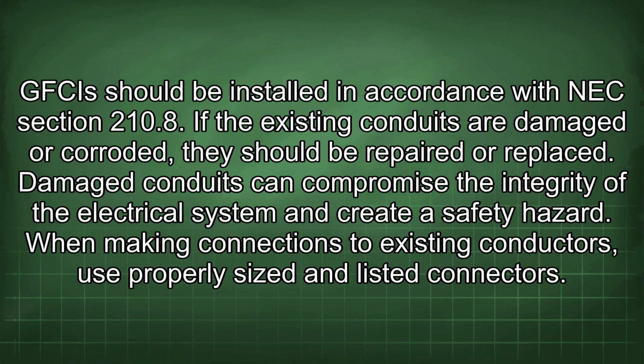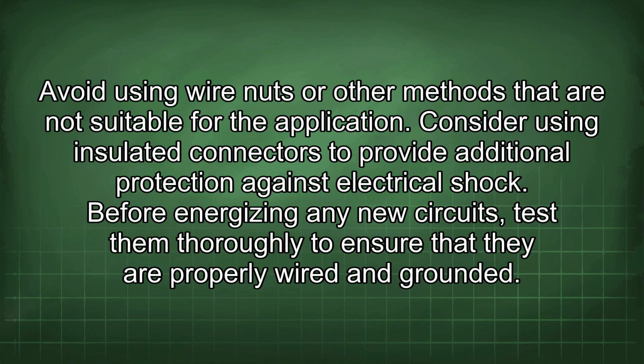When making connections to existing conductors, use properly sized and listed connectors. Avoid using wire nuts or other methods that are not suitable for the application. Consider using insulated connectors to provide additional protection against electrical shock.